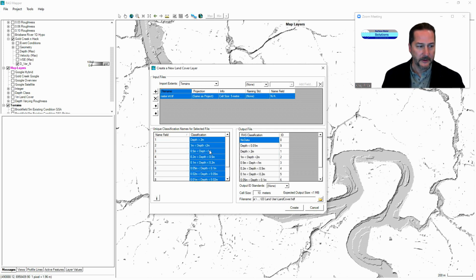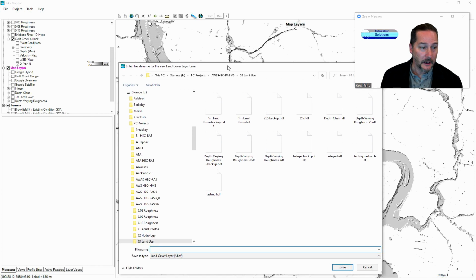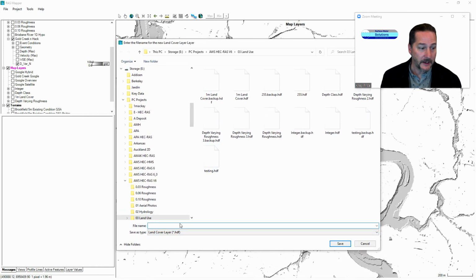So when I paste those in, you might have to do these one at a time if you can't get it across the whole range. But you'll see here what these categories are going to be. Just to match some of my previous output, I'm going to change this to a raster gridded cell size of 5 meters by 5 meters. And I do want to define this one so that we can give it a name here and refer back to it later.